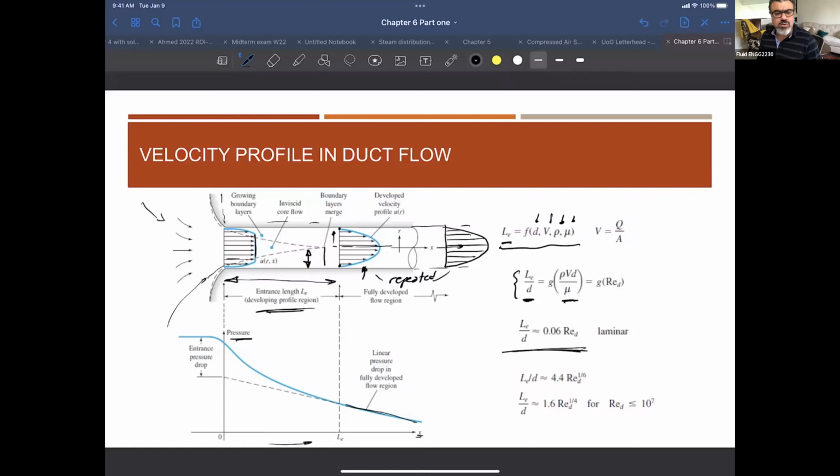Okay, what I want you to know from this slide is that the fluid can change because it goes through some variation. Like this huge tank, the fluid is almost stagnant inside. Now the fluid comes inside the pipe, and the fluid tries to reorganize itself, right? So it takes time. Which means that there is something called developing length, like a flow that is developing to the point it becomes almost repeated with the same characteristic later on. So this fully developed length depends on the flow characteristic, whether this is a very fast flow like turbulent flow or laminar flow.